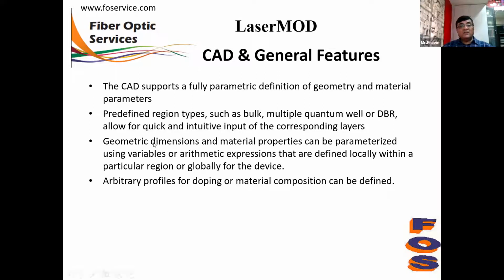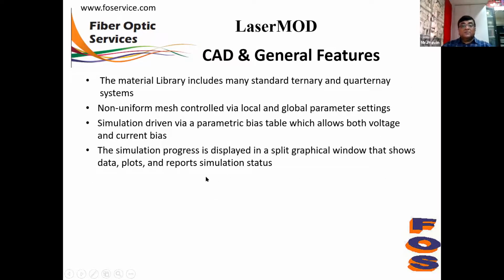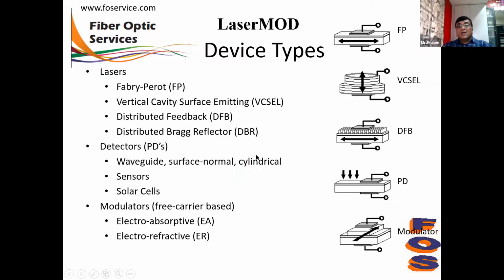It has predefined regions like multiple quantum well, DBR, and so on. It also has non-uniform mesh control. The material library also has ternary and quaternary material systems, because the laser will use various kinds of dopants.